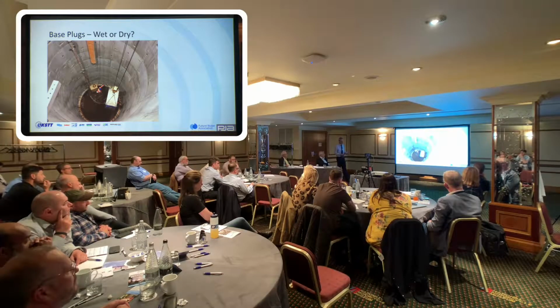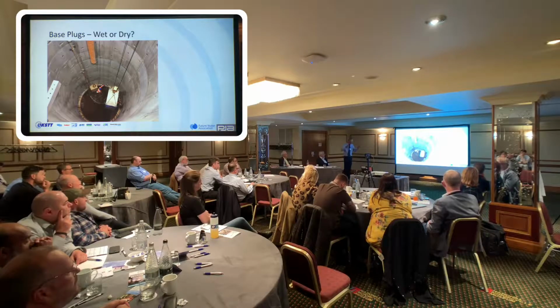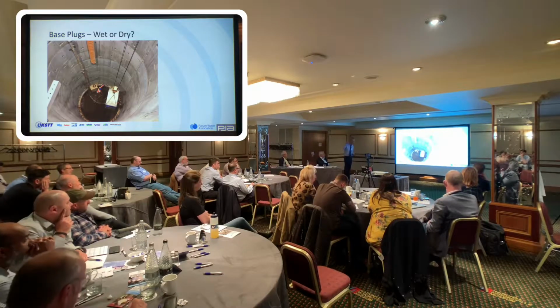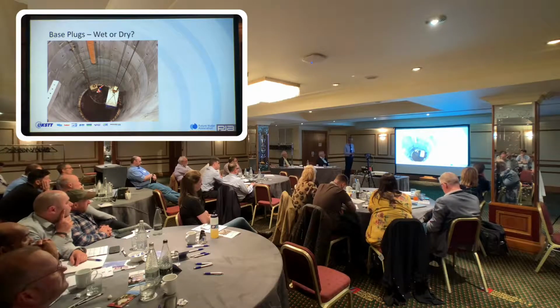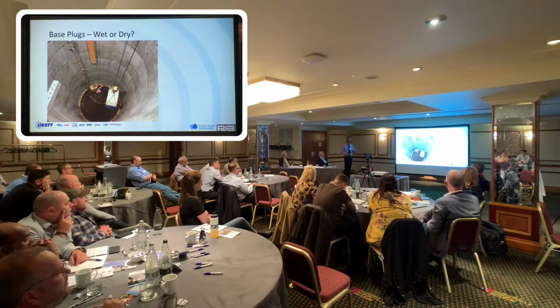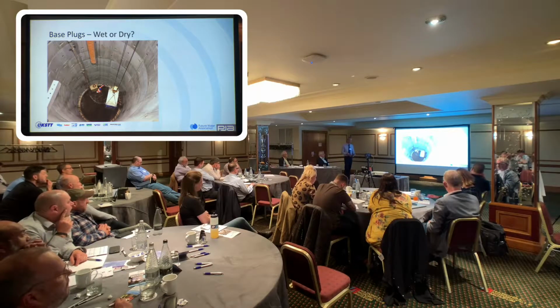Most shafts will need a base plug. If you are sinking a flooded caisson shaft where you leave the groundwater in the shaft and you excavate through the water, you've done that for a reason. It's because there's groundwater there and you can't dewater. In that instance, you would need to pour a plug underwater, so you'd pour the base plug through a tremie pipe. Ordinarily, it wouldn't be reinforced; it would just be over deep and a mass plug.